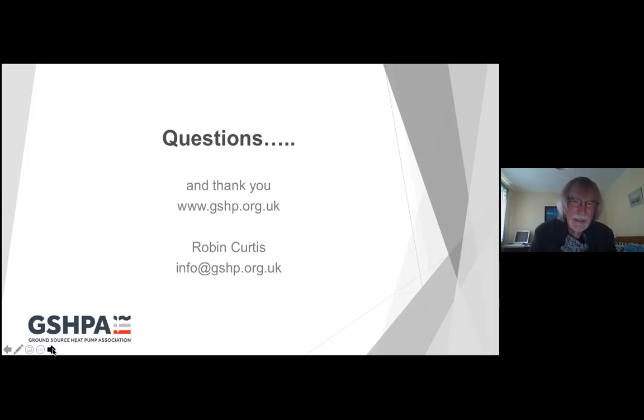Well, arguably, yes, a bit. I don't know how many companies are offering them, but Movitech actually have a technical paper out in which they attempt to demonstrate the improvement. The trade-off is that you possibly get some increased heat transfer due to the rifling, but there will be a trade-off against some increased pressure drop due to the rifling.